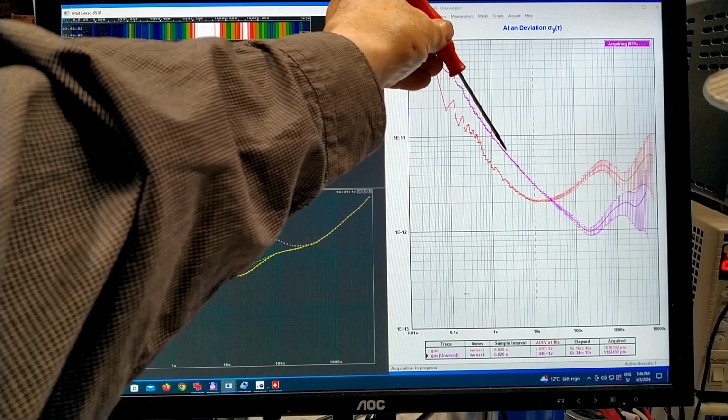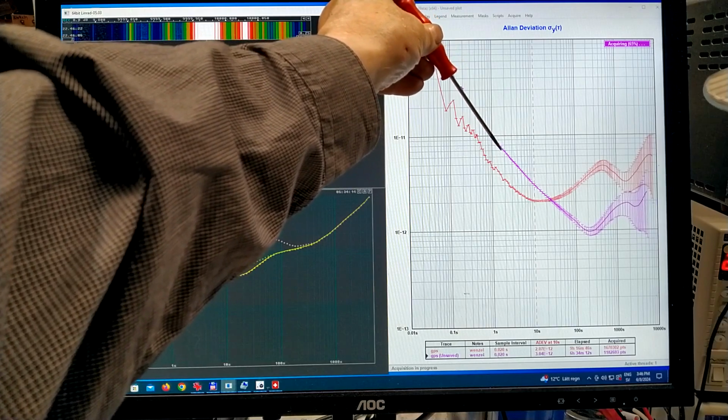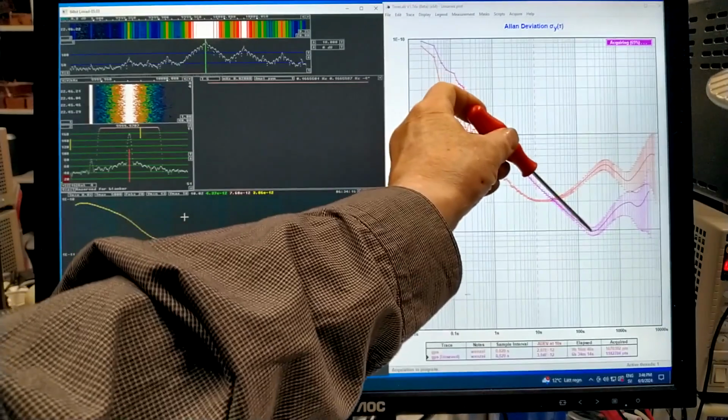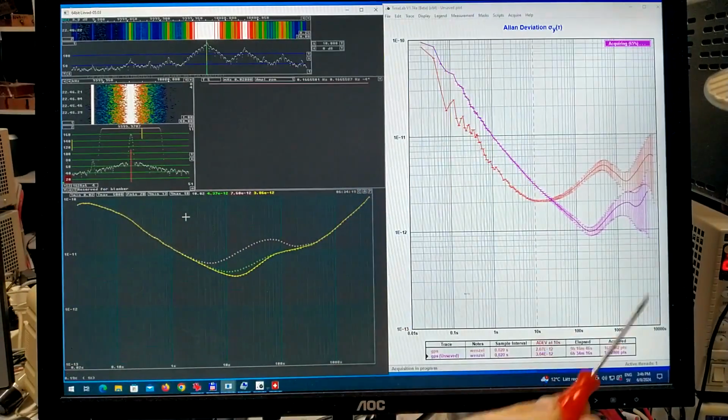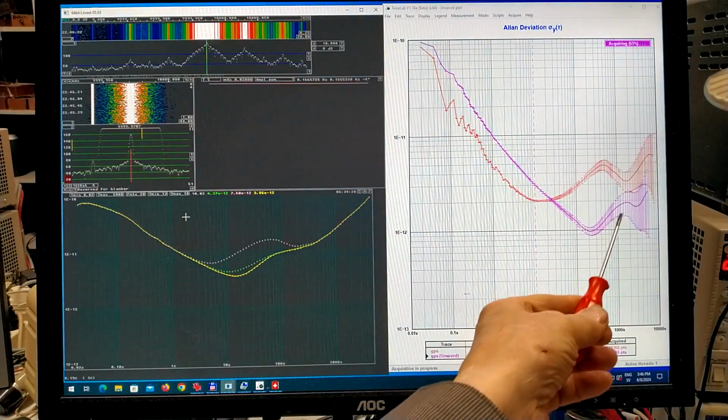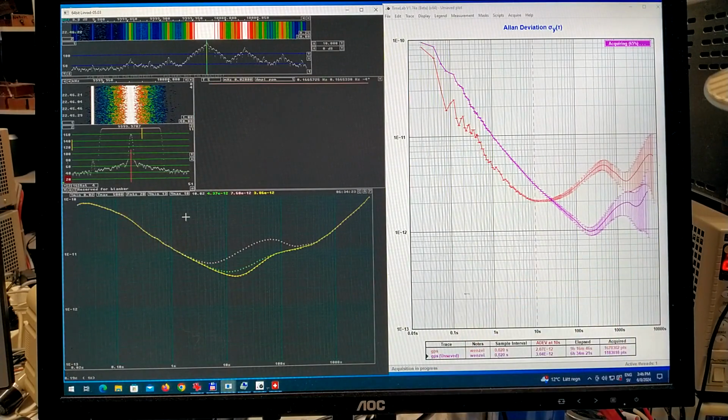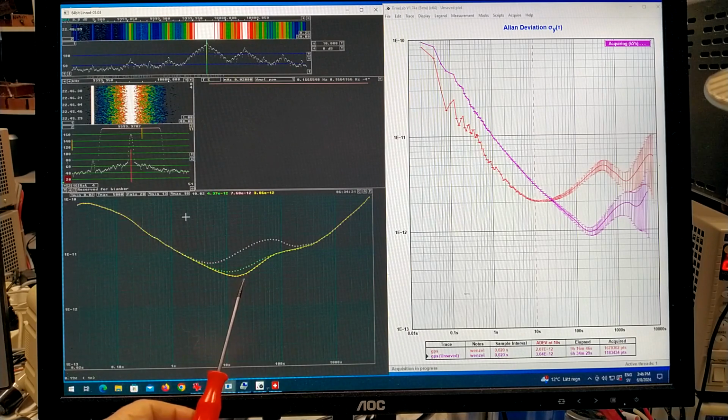And here is the noise of the rubidium-controlled oscillator all the way down here. Then probably what goes up here is the noise of the Wenzel oscillator, because that is the reference. And in Linrad, I have not waited long enough to see the full correlation picture.